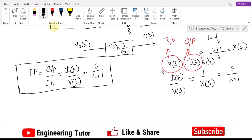Okay. So, when any signal, let's say a DC, is applied, it will be multiplied with T of S. T of S will be multiplied by V naught of S, which is the input, and it will give me the output. Whatever the input is, you have to transform it to the Laplace domain and then multiply it with the transfer function, and you will get the output. Okay.